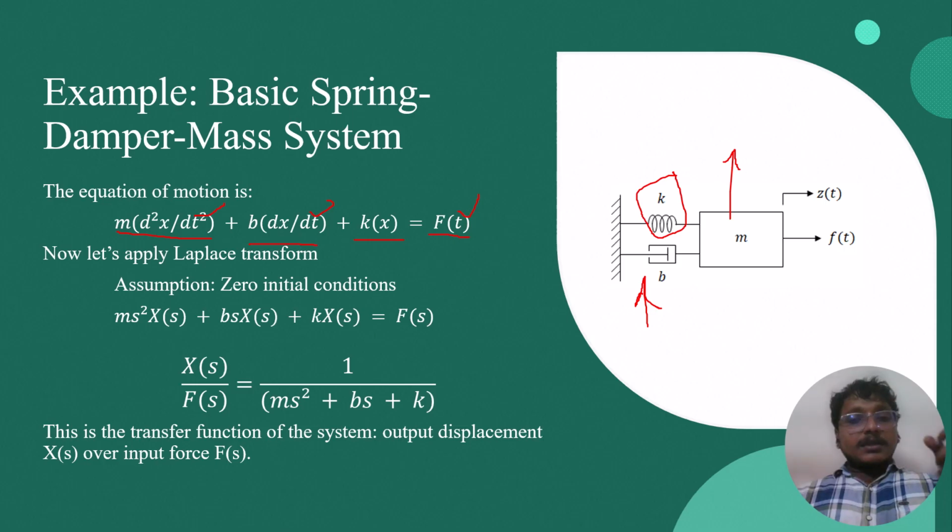To understand the simplification, that's why we convert the time domain to the S domain analysis, which is called the Laplace domain. To convert that, we need to apply the Laplace transform to the above equation. Then automatically we can get the S domain equation. But here we are taking one assumption; assumptions are very important in control systems. The first basic assumption is that the initial conditions start from zero, without any before or after initial conditions. So the initial conditions are always considered as zero only.